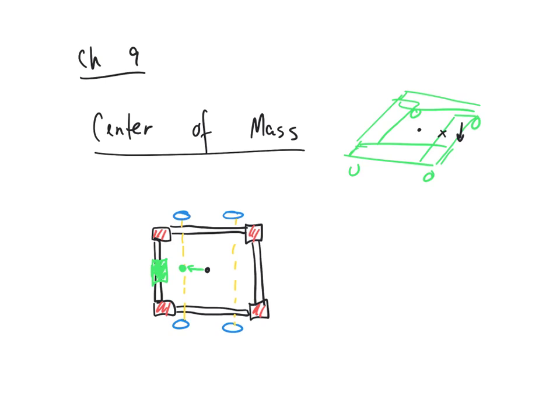Again, though, this assumption is that what? The material is the same throughout. There's a word for that in physics or engineering. It's called isotropic. An isotropic material means that its physical properties don't change based on its location in the solid. So it doesn't suddenly become more dense.